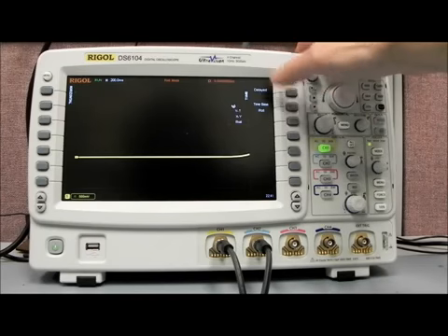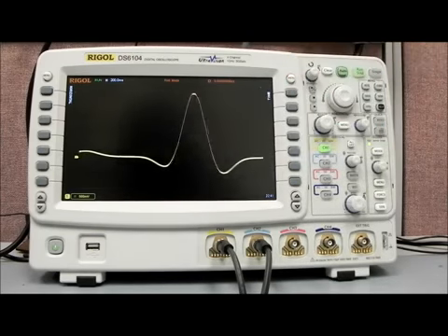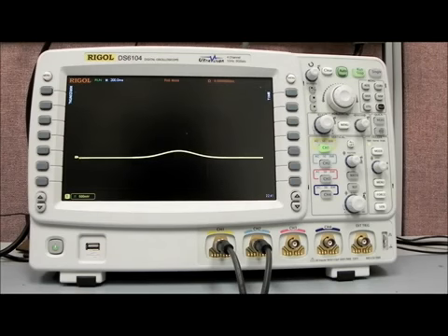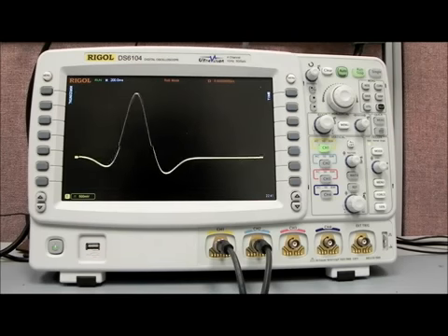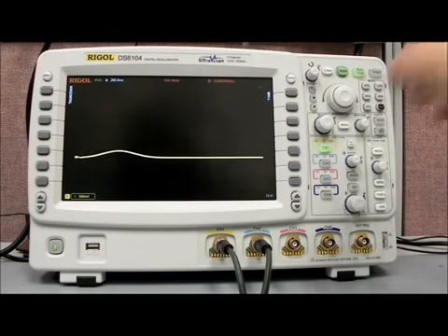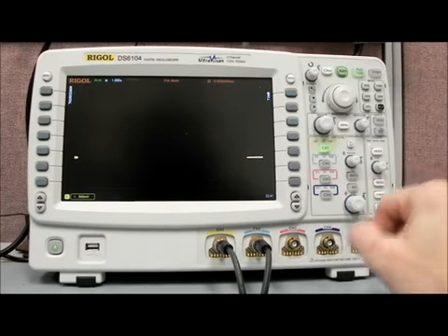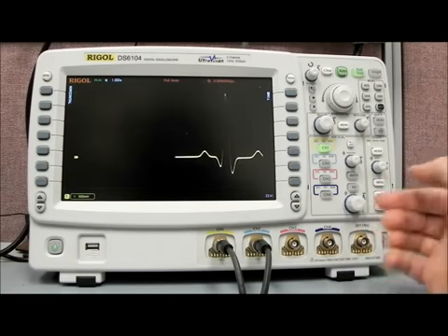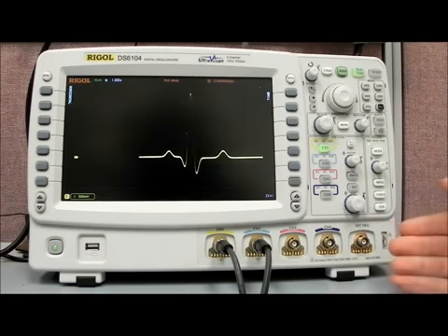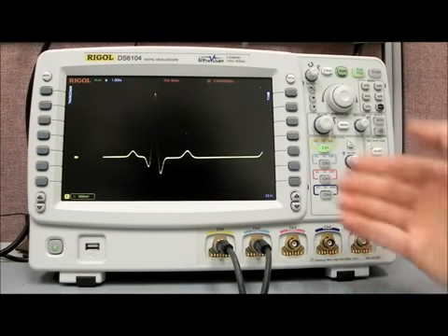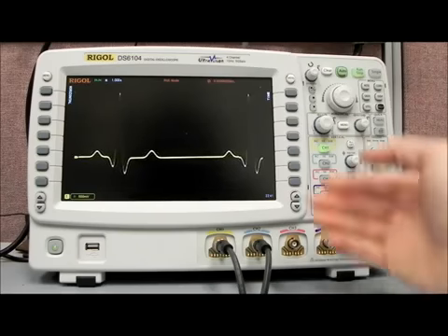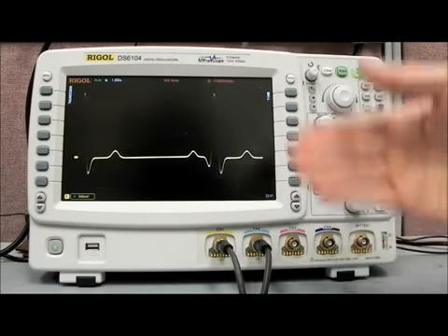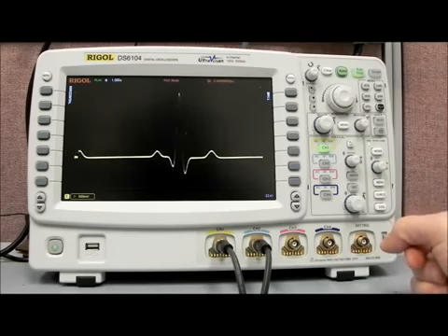Again, in the horizontal menu, we can select roll, and now we're getting a rolling display that updates automatically from right to left. So it's not acquiring data and then displaying the data, it's more of an active acquire and display for each of the data points, and you can see it's rolling right along. You can also decrease the roll rate, much like an EKG machine in a hospital. If we had a time-varying signal that was very long, let's say below 10 hertz or so, this is another way of displaying the data, and it will actively show you what's happening in a continually updated fashion. It can be useful for slower signals.